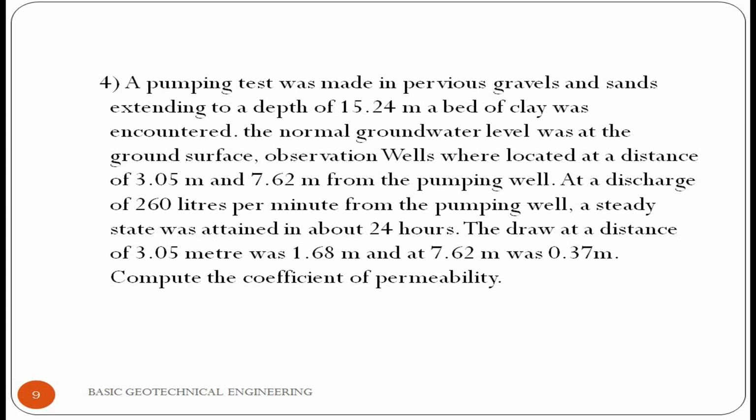Observation wells were located at distances of 3.05 meter and 7.62 meter from the pumping well, at a discharge of 260 liters per minute from the pumping well. A steady state was attained in about 24 hours. The drawdown at a distance of 3.05 meter was 1.68 meter and at 7.62 meter was 0.37 meter. Compute the coefficient of permeability.